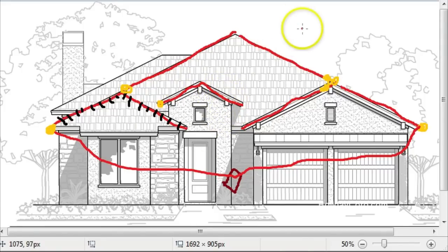Now, that said, there are some controllers that do feature what are called phantom pixels, where you can put in pixels that basically don't light up. They're just there to repeat. So the signal comes out, there's one right there, one right there, one right there, one right there. So the signal goes from here to the controller, here, to here, to here, to here, where it actually starts operating.